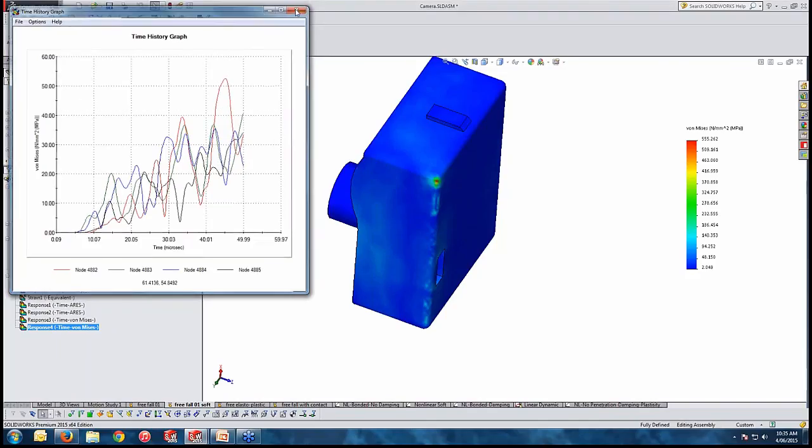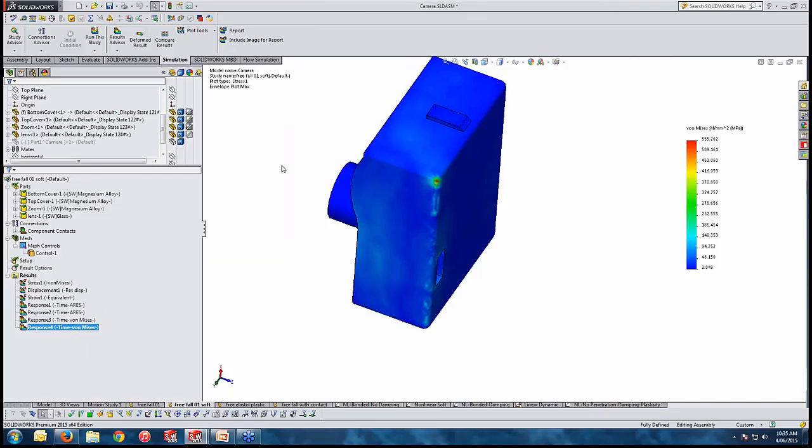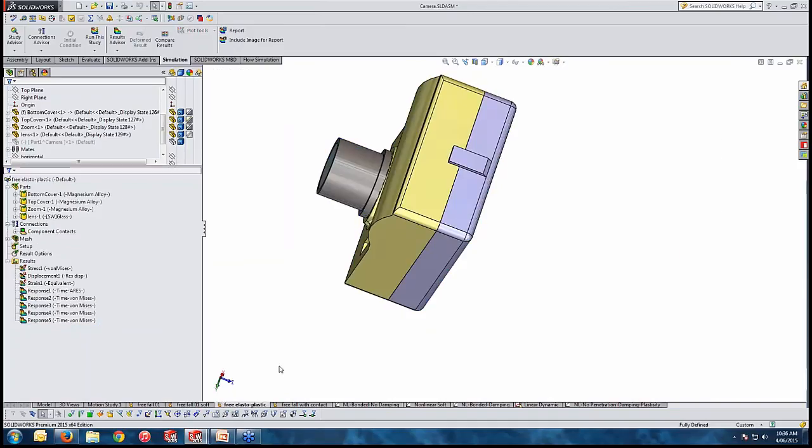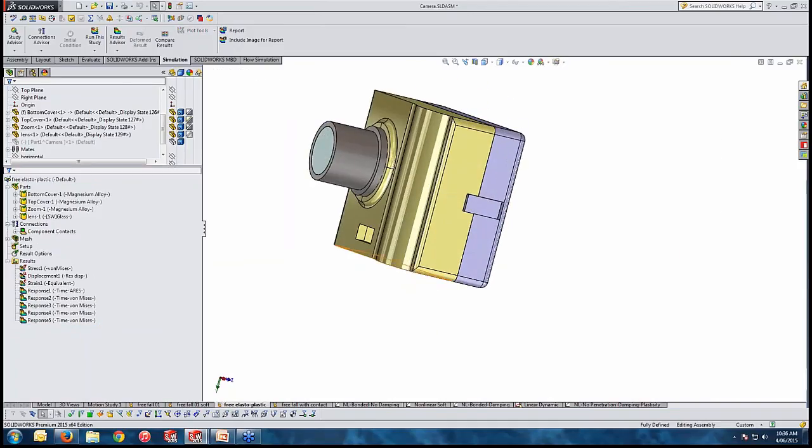Good. Now we are trying to make the case as close to reality. That's why I'm going to have the third case study. This time, as we know, when such an impact is happening, we have some permanent deformation, or let's say one of the materials is going to permanently fail and we have plastic deformation on it. Therefore, the material should be modified to capture the plastic deformation on the model.